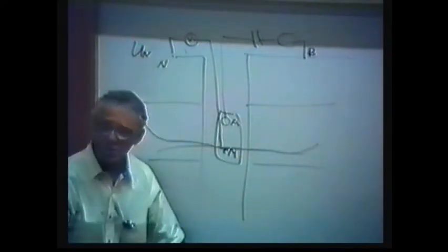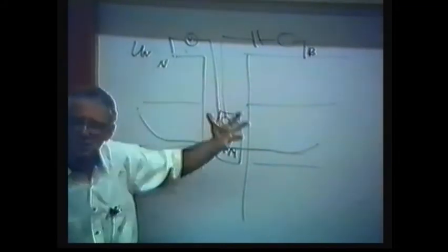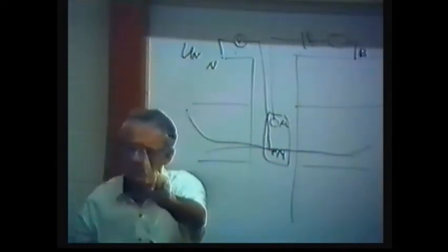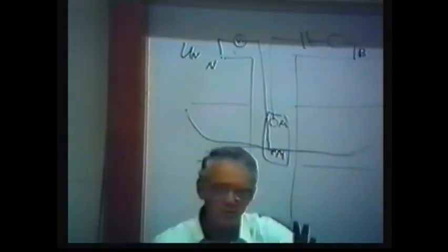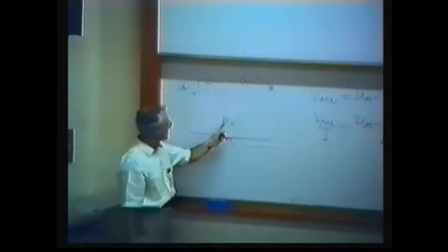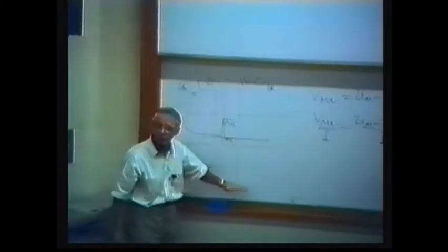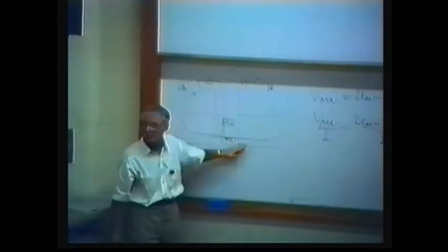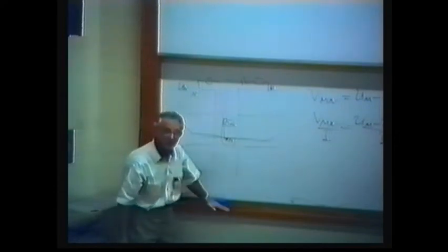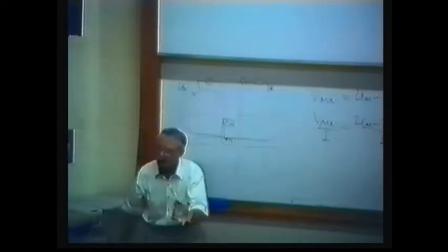That's infinity. So the normal probe, or potential probe, has two names. In Europe and in North America, the normal probe, one of the most popular probes, measures resistance of the whole medium beneath the receiver electrode. Now let me show you another popular probe.